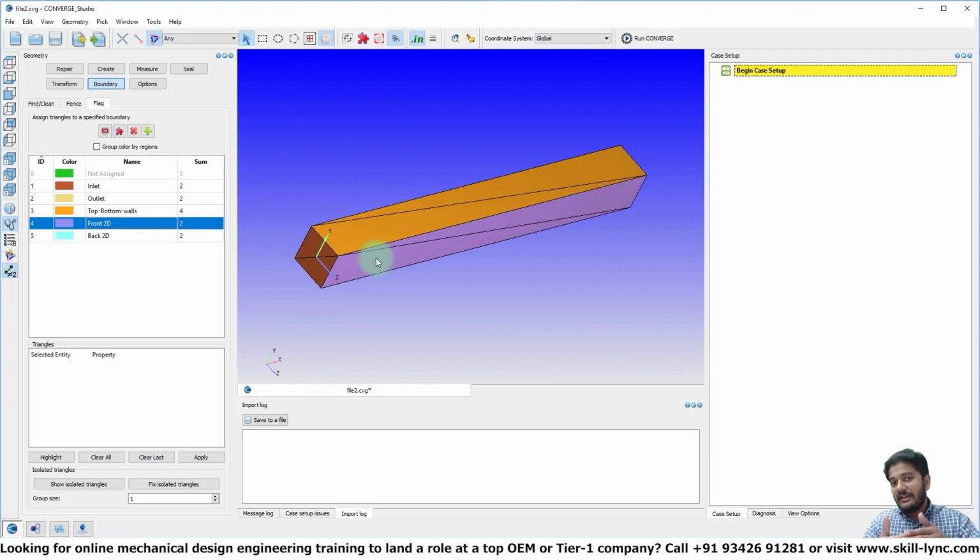It's basically like you have a really large cake, right? If you have a really large 3-layered cake with cream in between, you make a slice anywhere, it's going to look the same, right? So you basically create a slice and you're saying, okay, I'm just going to simulate flow in that slice. But in order to identify that slice, you need to select the front and back of it, right? And that is the direction which you are trying to ignore, correct? And that is why you're selecting the front and the back side. I hope that this makes sense. If it doesn't, feel free to let us know.